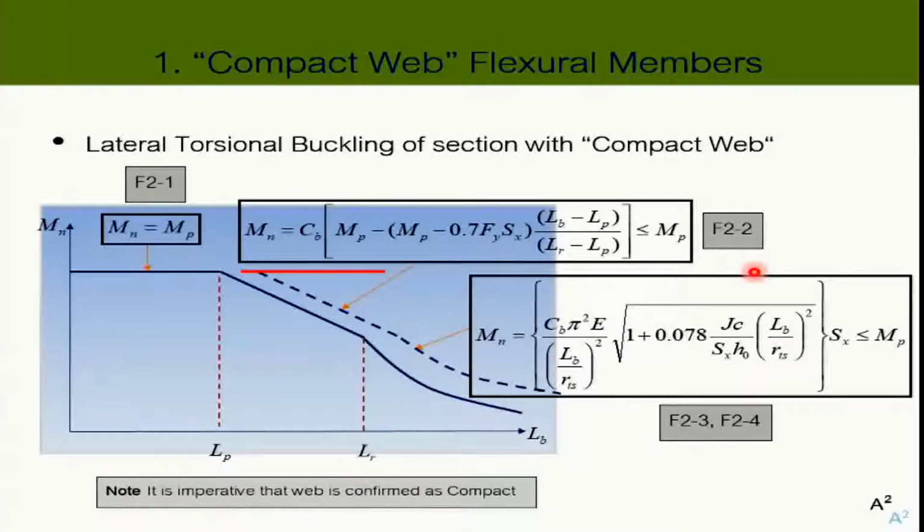It doesn't take guts to use CB, you know. It's just the factor that reflects the true behavior of our structure. So I don't know why there's that idea circling amongst engineers: just use CB equal to 1 to be safe. But if you use 1 and the value is 1.67, just my case, for example, you're losing 67%.